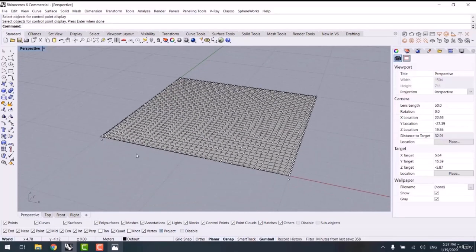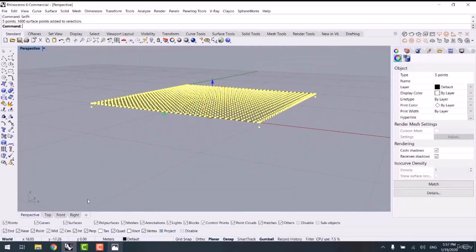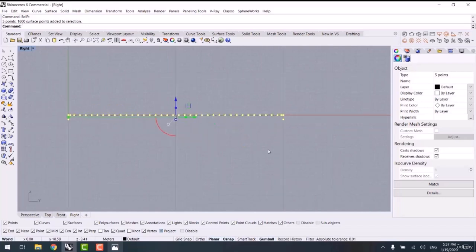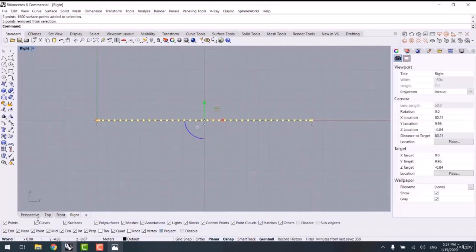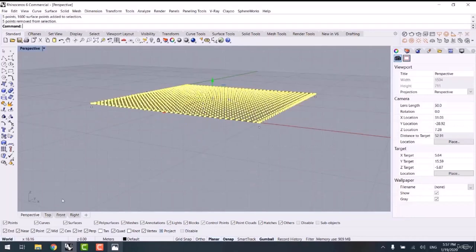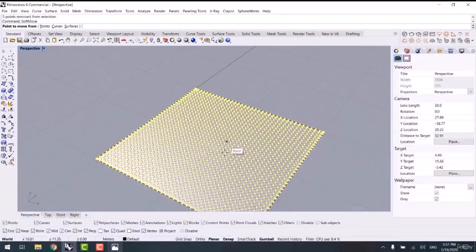like this way. Following that, I turn on the control points and then soft move, selecting points. I select all of the points by select points. After that, at the right view, I hold down control button and then I deselect the 5 added points, like this way. And then it's time to start soft move.